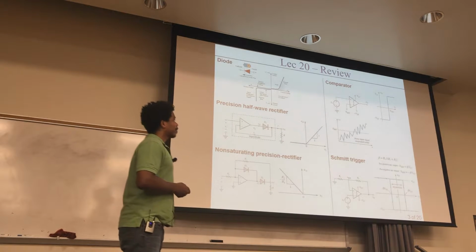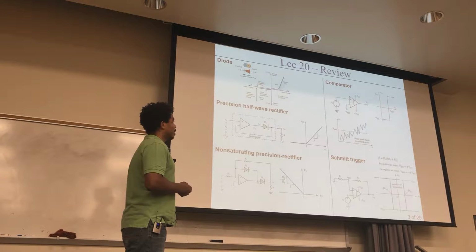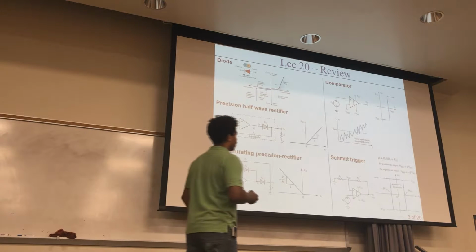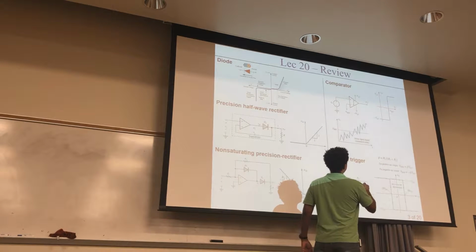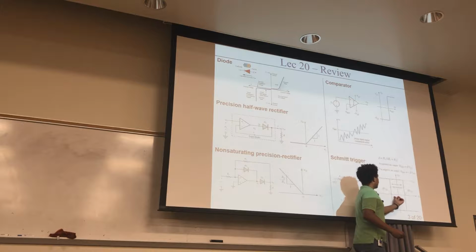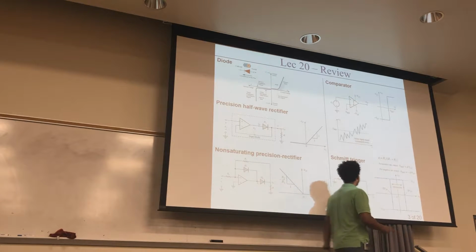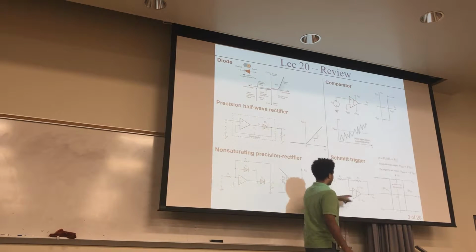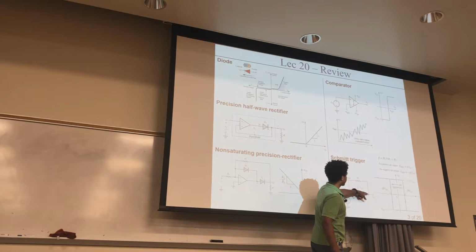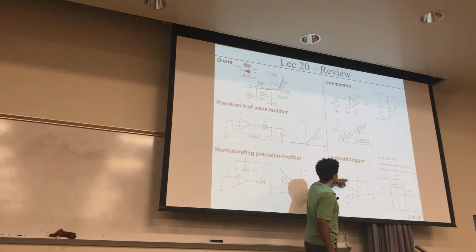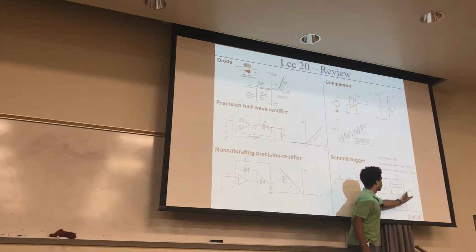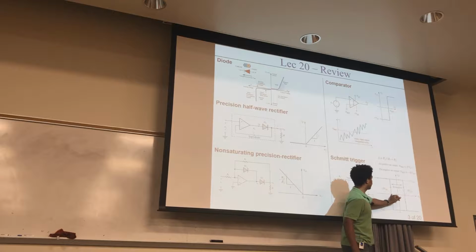A good way to deal with that is to use the Schmitt trigger right here. It actually takes this piece right here and widens it up, so now you have this hysteretic effect. Even though the output will go to its saturation states of VCC and VEE, as soon as it goes to a saturation state, it changes what your reference is from beta VCC to beta VEE.